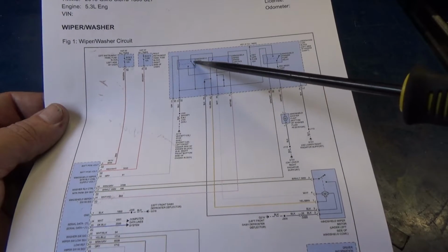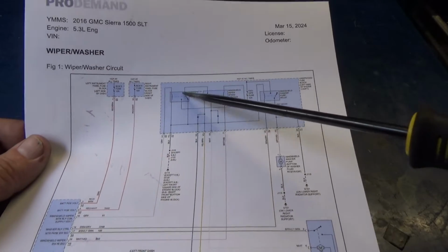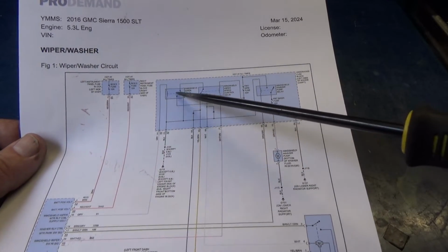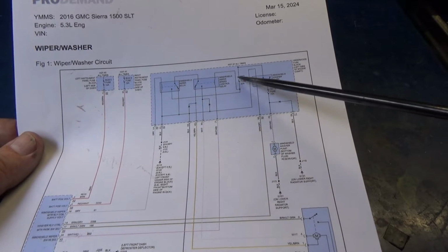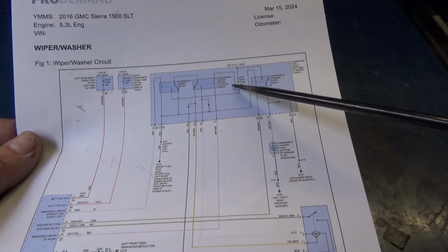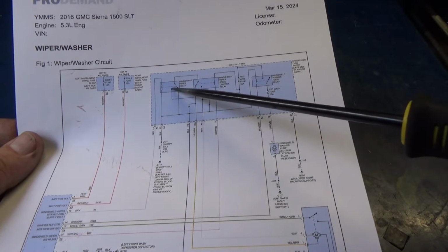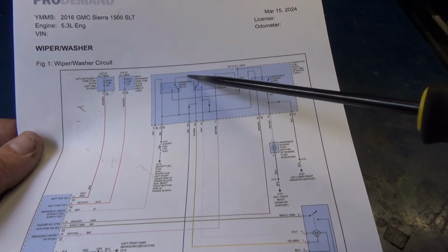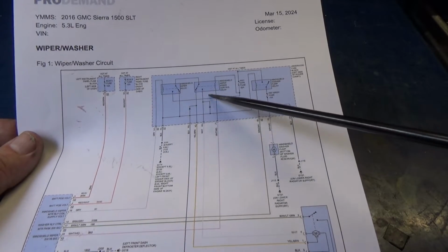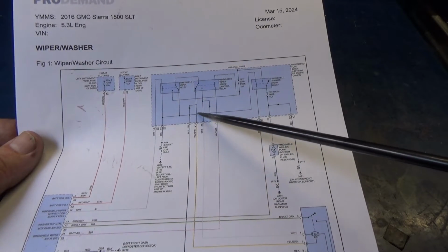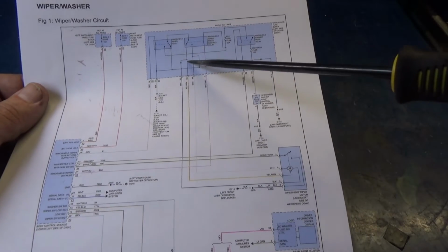When that happens, this set of contacts is going to slam over here and make contact with this set of contacts right here. When that happens, you've got power right here at this fuse. So we now have power going through this set of contacts, coming up through the relaxed or de-energized high-speed relay. It's going to shoot power down here.